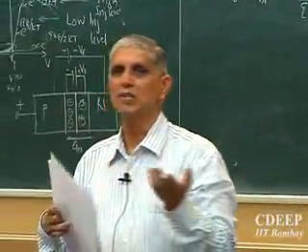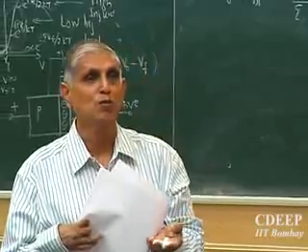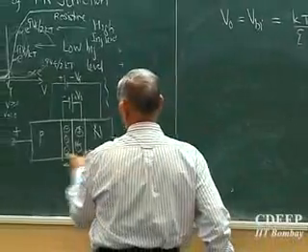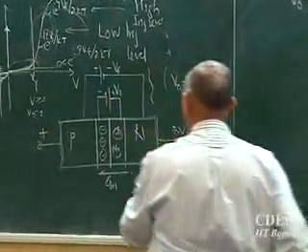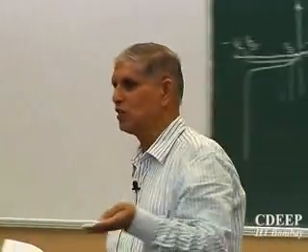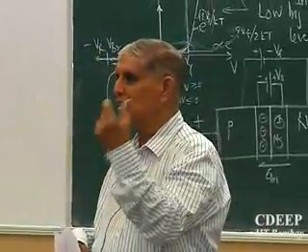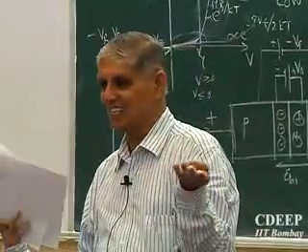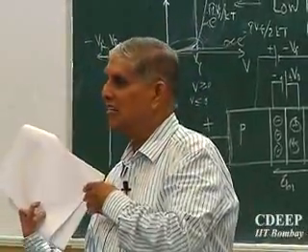And if that is so, where else is the voltage going? Somewhere the remainder voltage must drop. Which regions can it drop in? Yes, it may drop here, it may drop here, it may drop at the contacts. But the diode junction will only get VF, which is less than V0. If V0 and VF are equal, there is no junction barrier, everything can pass. That's exactly what happens when you come closer to V0. Is that clear? V0 minus VF is 0, which means no barrier, everyone can go anywhere, like a resistor. Okay, so there is a limit essentially.